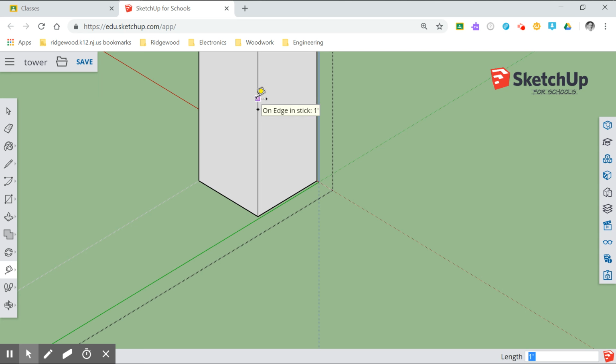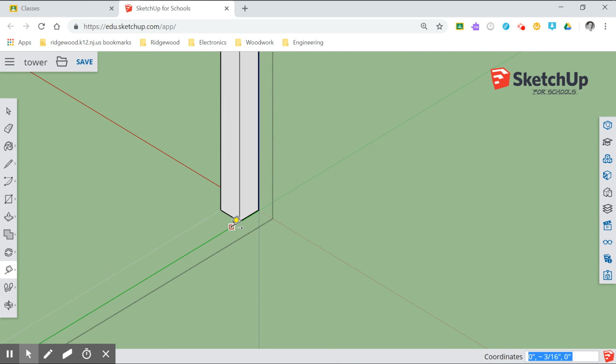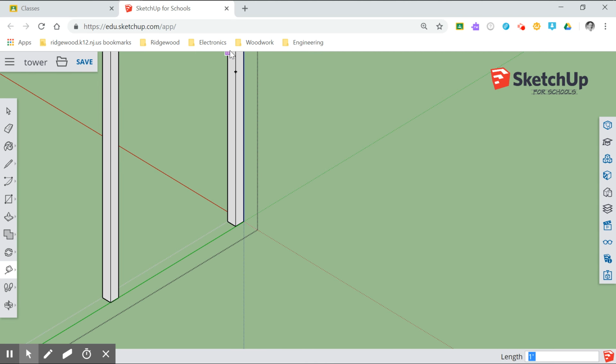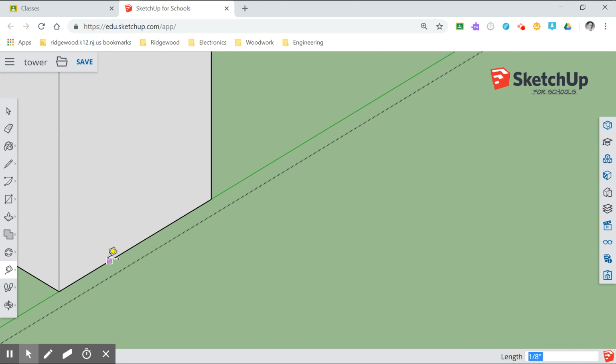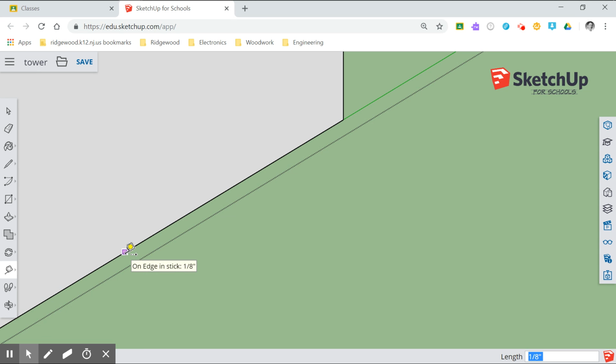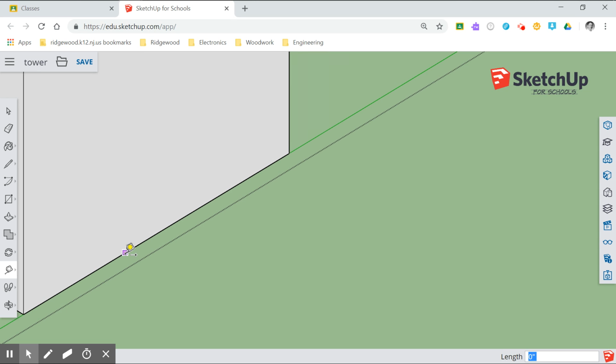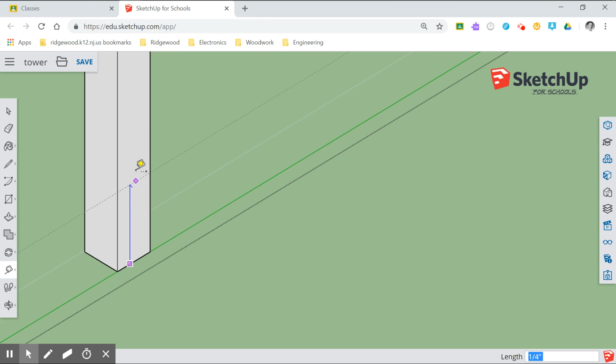So if I click on a point, and then I go ahead and draw it up a point, click again. Let's say I type in 2 inches. I want it to be at 2 inches. Okay. It created just a small point. Okay. So guide points will happen from a point. Okay. If you want to do a complete line, you need to reference it from another line.